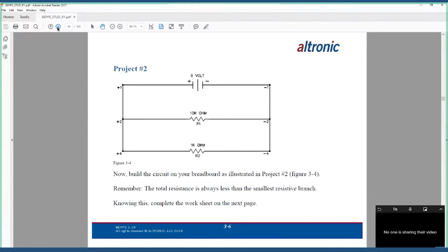If we go back to last week's lesson, when you're measuring the resistance on a component, remove it from the circuit, do you remember that? You remove it because you don't want other things in the circuit throwing it off. So you check it out and say, well, man, it's working great. But then you throw it back in the circuit and it's still not working. Well, something might be wrong with the circuit, obviously, right?